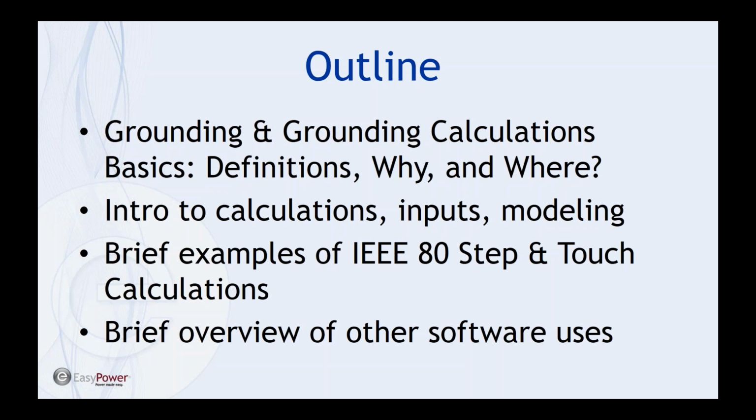Power and electrical system grounding is a massive topic and can be very confusing. So today we're just going to go over the basics of what the calculations are, where and when to use them, with some examples from the real world sprinkled in. So like I said, we'll cover grounding and grounding calculations basics. It's kind of the definitions, the why and the where. We'll get into an intro to calculations, inputs and modeling. Then we'll cover some brief examples of the IEEE 80 step and touch calculations and some software examples. After that, we'll do a brief overview of other software uses.